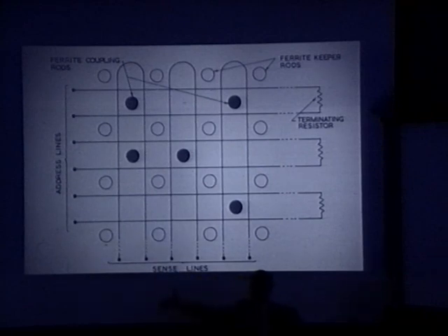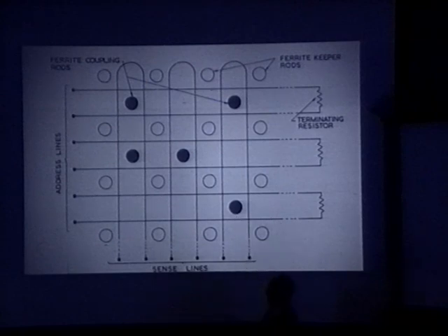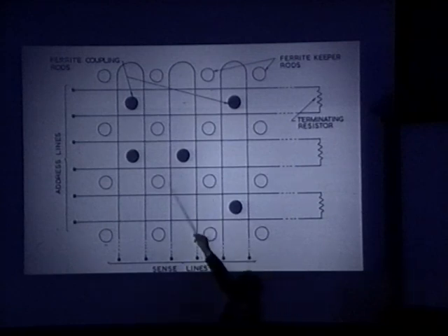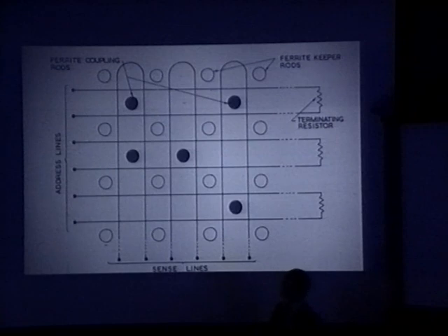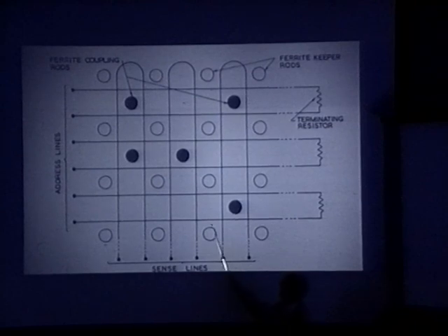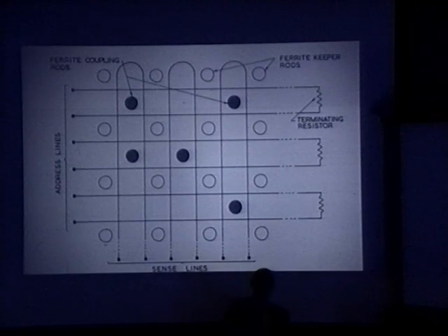And the mat was, as I remember, about so big, so high, and little ferrite rods about ½ an inch long, as I remember, would be inserted in positions where you required a 1 and omitted where you wanted a 0. The white positions here are keeper rods, which were always inserted to complete the flux path for the 1s.